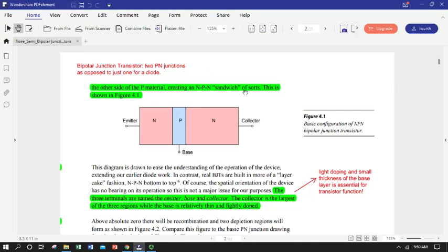Okay, so we're now looking at figure 4.1. And this is a very rough and simple schematic of a bipolar junction transistor, including our external semiconductor materials. These transistors come in two flavors. Basically, we can either have two regions of N-doped material with a layer of P-doped material between them, or we can have two regions of P-doped material with an N-doped material between.